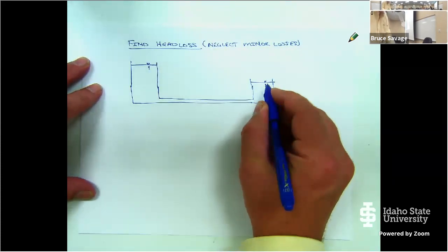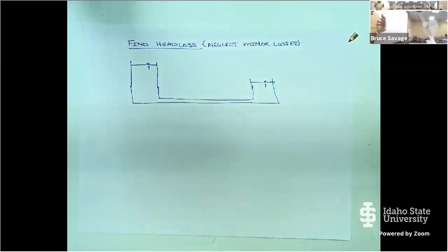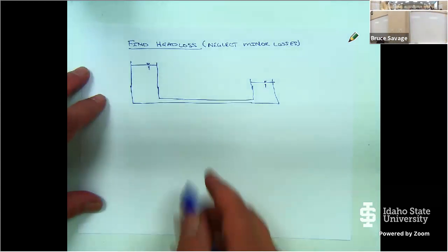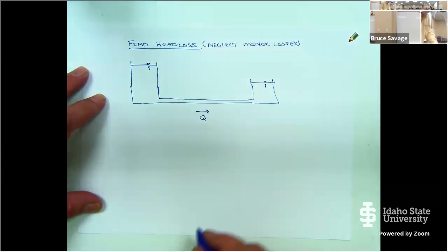And the question that Anthony asked us about, well, how do pressures relate? Beautiful. I mean, that just led right into this, because once again, these reservoirs are symbolic, they're representative of the total energy. You know, so I'll have to send you a check later for asking that question, but it's great to point out the fact that we can have pipe pressures, we can have elevation changes, we can have reservoirs like this, we can have pumps, and we're going to add pumps later on, and we just convert them into a representation of the energy.